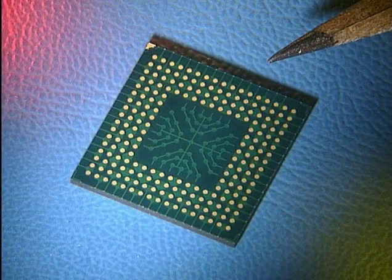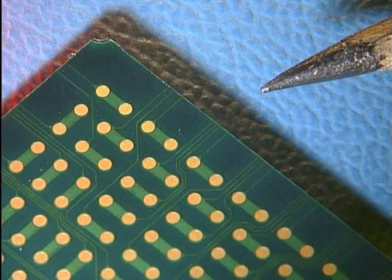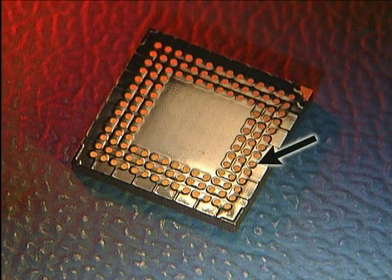The last type of array-style component we'll mention is the land grid array, or LGA. For identification purposes, an LGA is simply a ceramic BGA or CCGA without the balls or columns. They are simply a series of flat pads or lands that are soldered to corresponding lands on the circuit board.